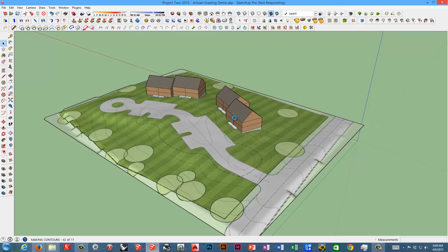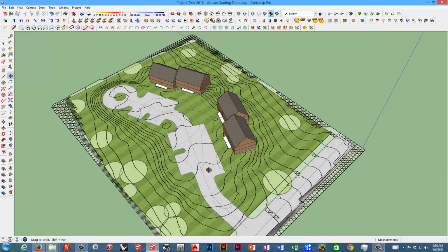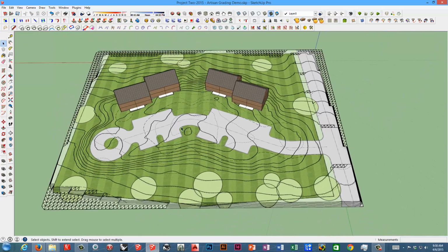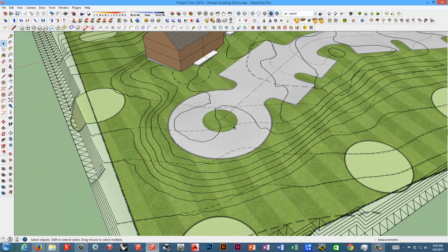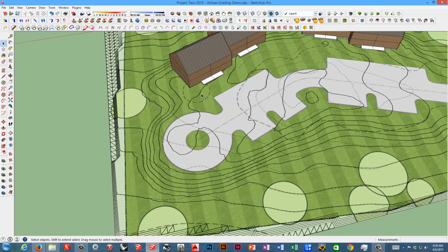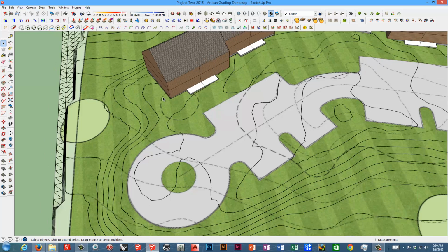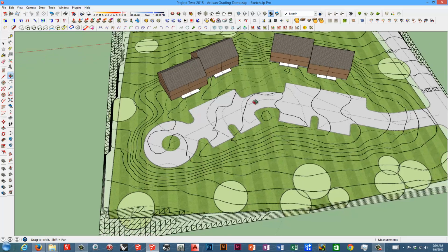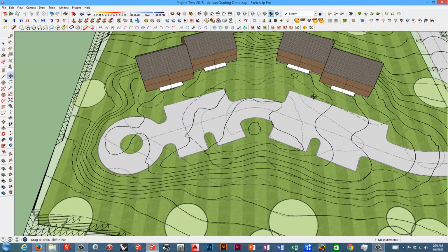So as you'll see here, the contours actually do line up pretty well. So there's my proposed contours. You can see I still need to do a little smoothing down here. But you can get the basic drainage pattern, and you can see clearly we've got some water running into the buildings, but these contours can be pulled across and brought in this way so the water runs out. But basically it shows this high point in the center, water draining both directions.